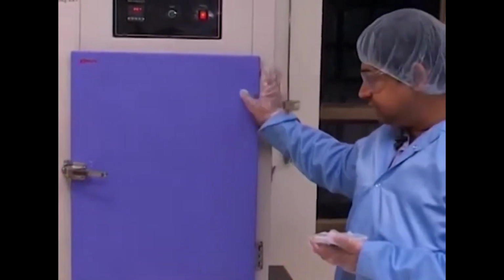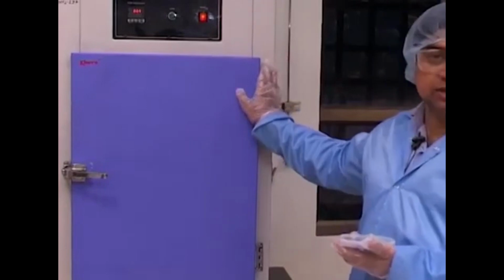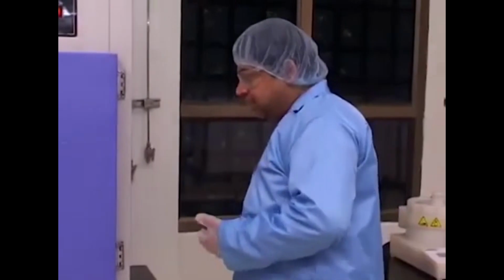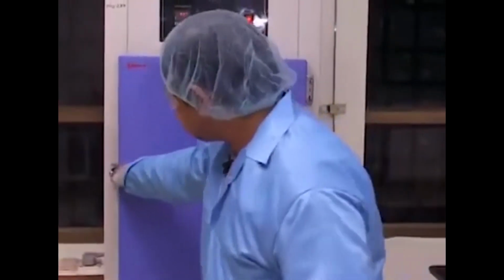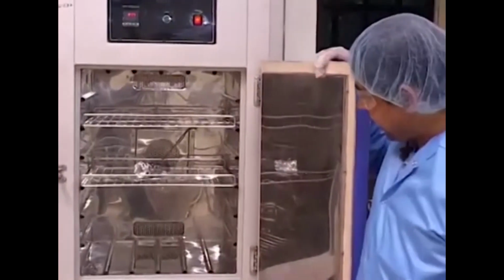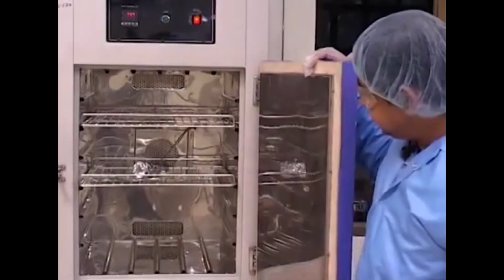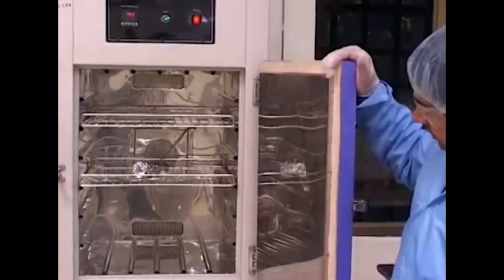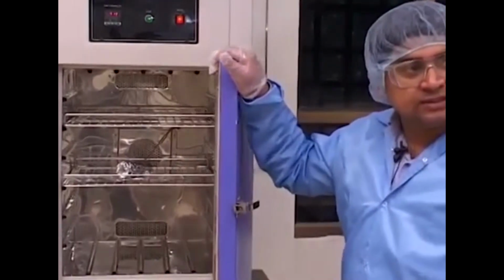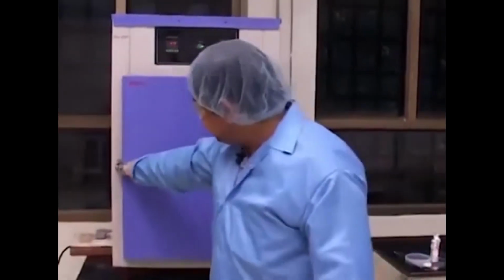So what I am going to do is to illustrate a little bit about this oven, and then basically use this oven to heat dry the wafer surface. So basically, if you look at this oven, really it is a shelved oven. As you can see, there is a fan which actually does forced convection along this whole area, and essentially the wafers are kept at various levels. The thermocouple is somewhere at the bottom. That is one disadvantage of this particular type of oven, because it sometimes is not a very good indicator of the temperature that happens.